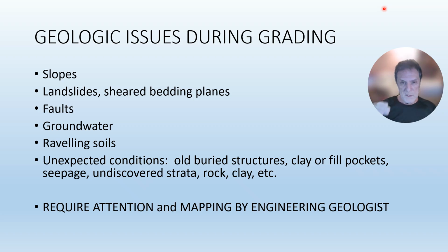With inactive faults, you don't have the issue of failure and generation of earthquakes, but they can act as conduits of water, and they can also contain sheared clays and unsuitable material, which may have some issues that you might deal with during grading. Groundwater, high groundwater, is always an issue.